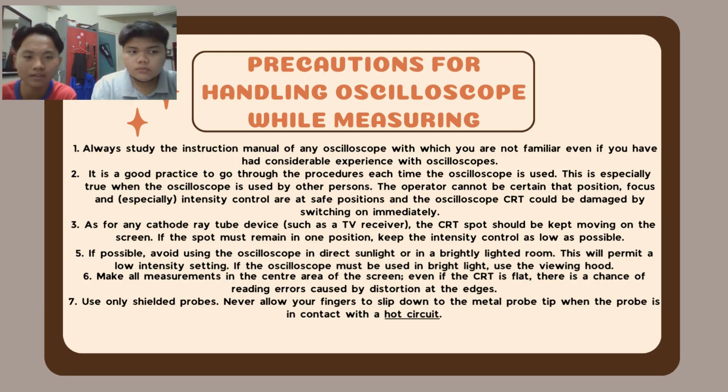Precaution for handling oscilloscope while measuring. Number one, always study the instruction manual of any oscilloscope with which you are not familiar, even if you have had considerable experience with oscilloscopes. Number two, it is a good practice to go through the procedure each time the oscilloscope is used. This is especially true when the oscilloscope is used by another person.